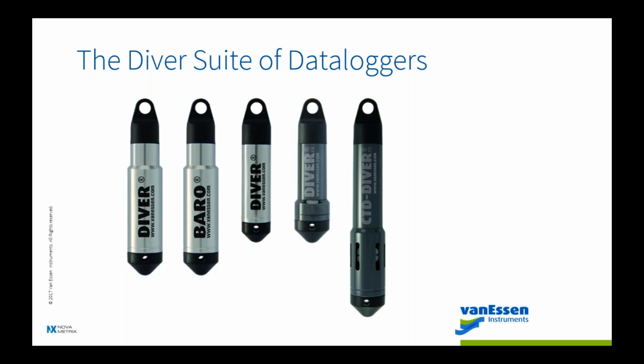A Baro can work in a 15-mile radius with whatever number of divers you have deployed there. These units, you just deploy one, covers that network of 20, 50, 100 in that 15-mile radius. But keep in mind that if there is a change in elevation of 1,000 feet or more, you may want to consider adding another Baro so that your readings are properly corrected.